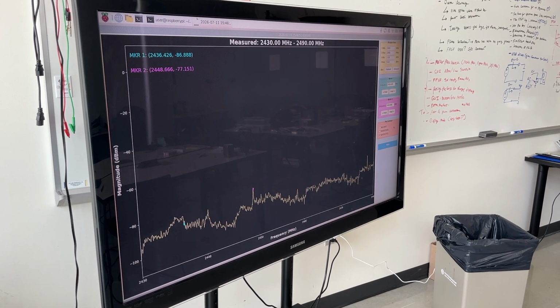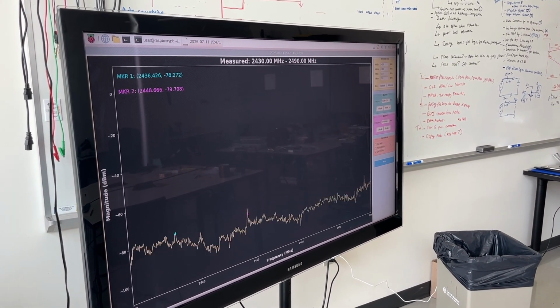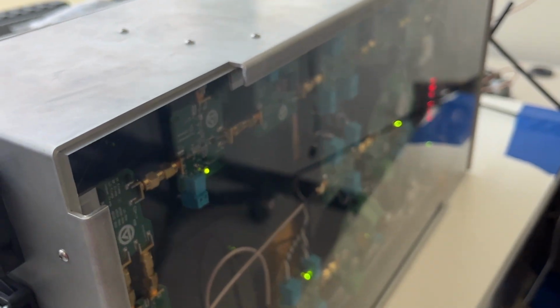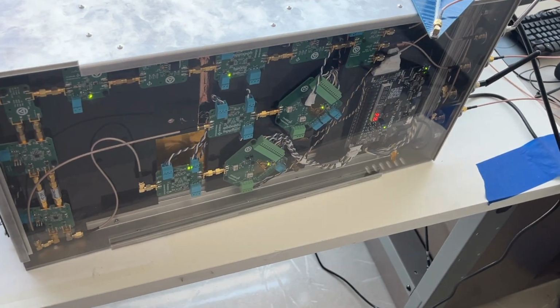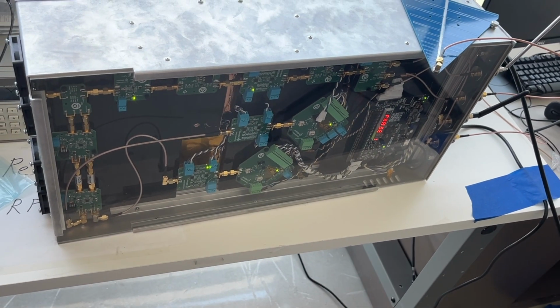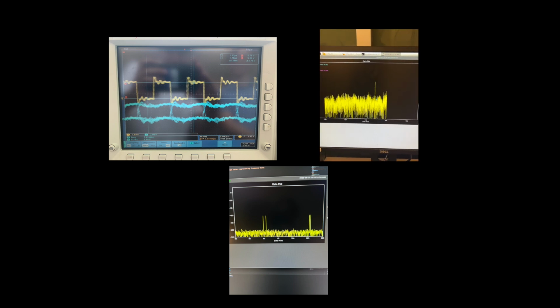Many of the major obstacles of the project have come from getting the spectrum analyzer to operate as one cohesive device. We were able to very quickly get each block in our block diagram to work properly. However, as with most RF designs, the trouble comes when plugging everything in together. Problems with noise, aliasing, and self-interference have caused many issues throughout the development process. Speed has also been a difficult obstacle to deal with.